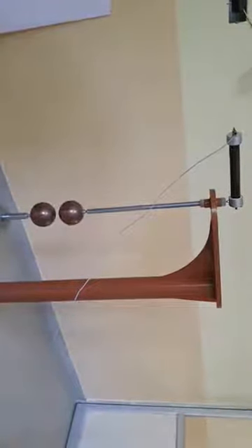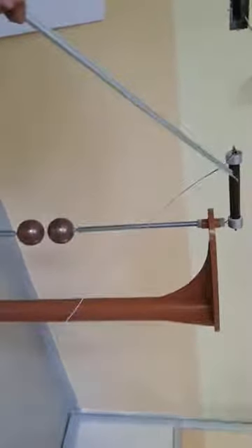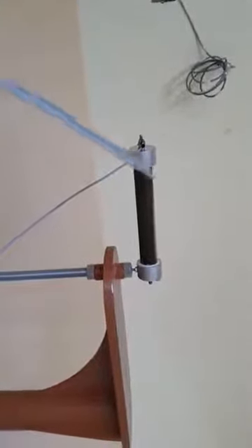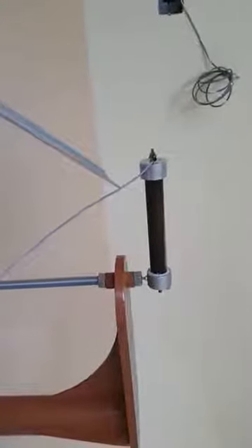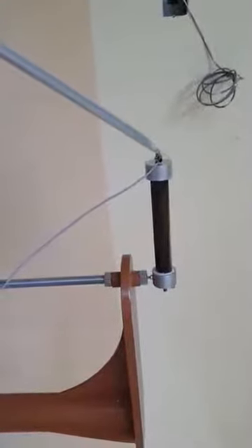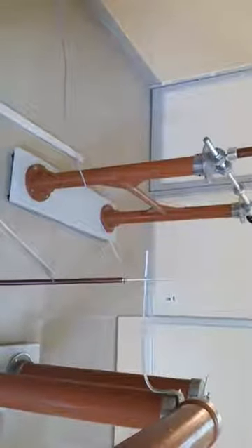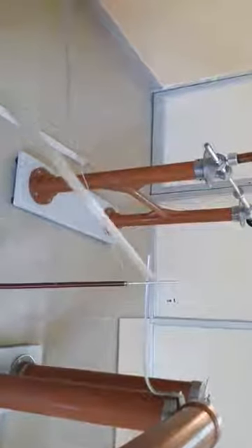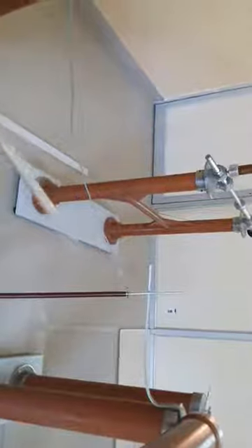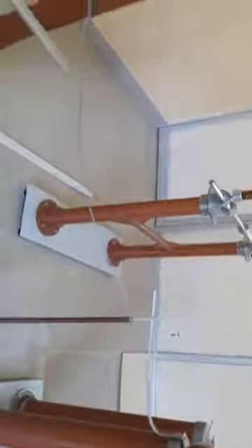of the control panel. And this is called a water resistor, for limiting the maximum current once the breakdown occurs. This is the terminal for connecting to the water resistor. Through this the supply is given from the high voltage AC or DC. This is the switching terminal, as I told you, for giving connection to AC and DC. Through this terminal the supply goes into the water resistor.